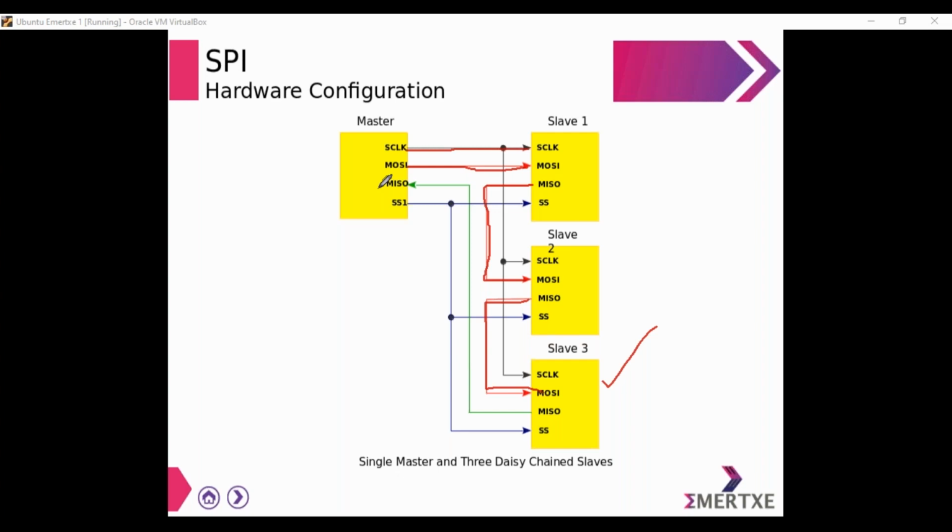So here, one drawback is, what do you think the drawback here is? Obviously, we have reduced the hardware configuration. The number of hardware lines are reduced. But what do you think is the drawback? Okay. It needs to traverse all the slaves every time. Yes, the problem here is with respect to the slaves. The data cannot be transmitted particularly to a slave. So privacy is not maintained. When data needs to be given to a particular slave, it is not possible.